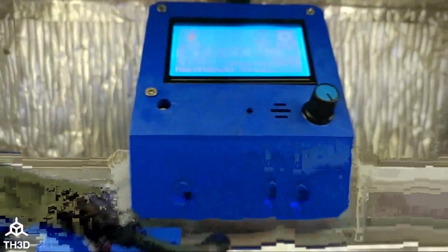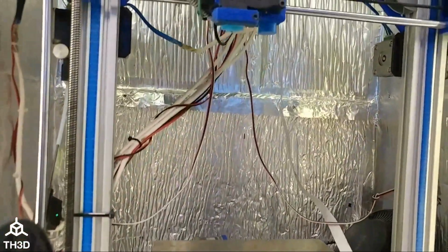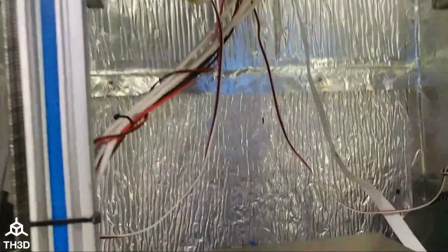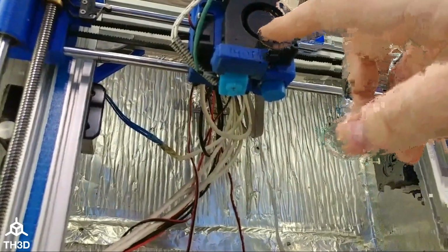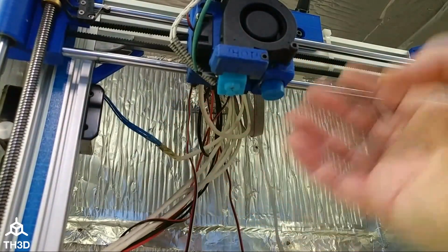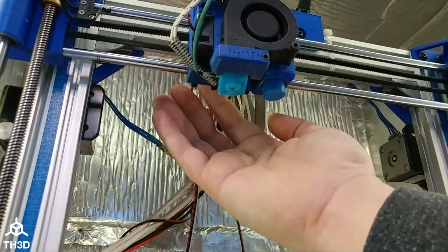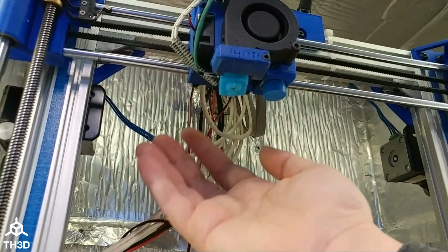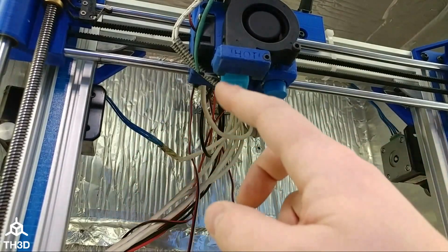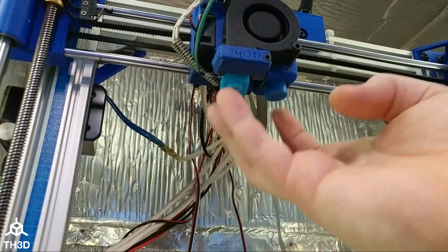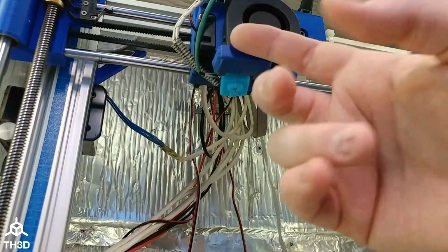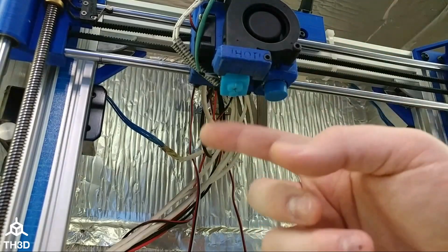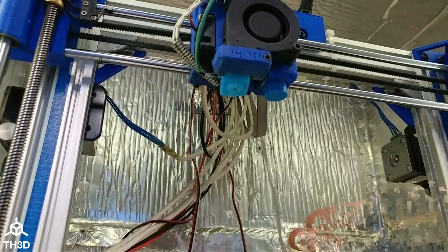Now, the silicone sock does help a lot, but it's best to do a PID tune with your fan enabled on the layer because you want to account for the airflow this fan's going to be putting out that could be dropping the temperature on your block. Now, these silicone socks are really great for keeping the heat in and resisting being cooled down from the layer fan. We run the silicone socks on every machine here.